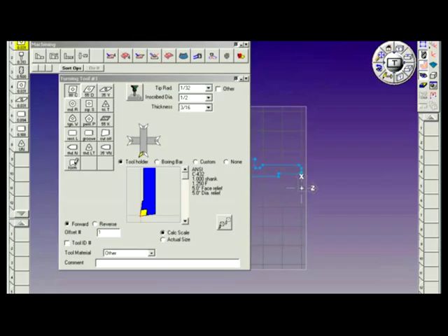A form tool is defined by drawing geometry at the origin of the part and applying it like a normal tool. When selecting a tool tile, you click on the tile and you come over to the tip radius selection drop-down menu and you specify the tip radius.